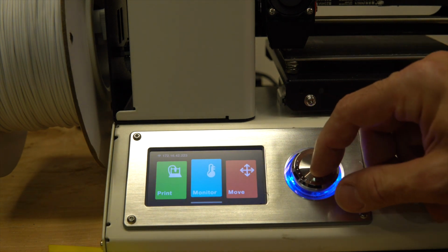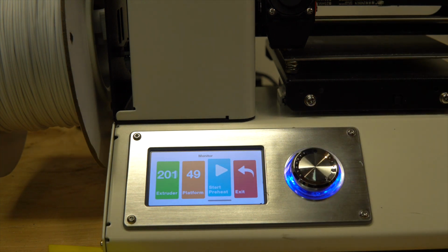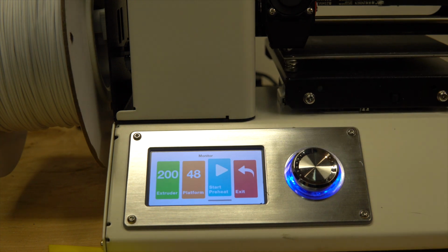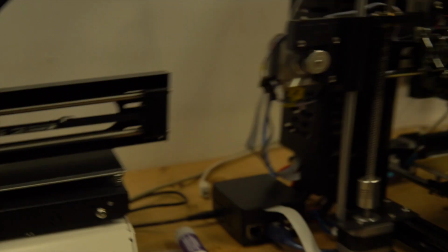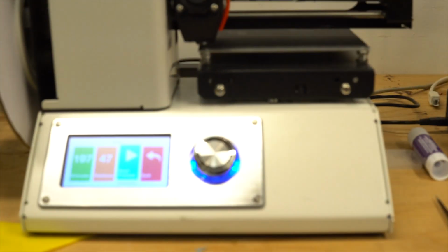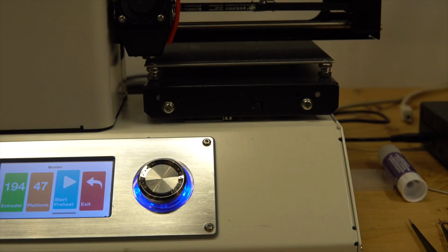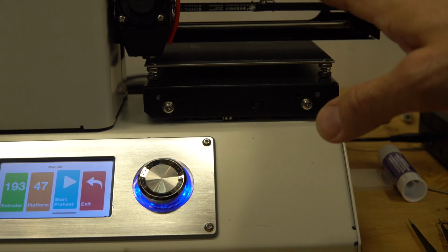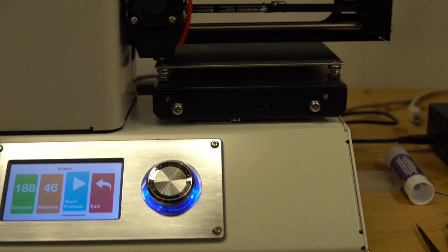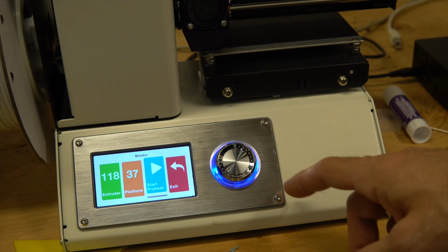Let's stop the preheat. So that's the bed leveling part of it. You know, you get used to it. It's nice to have an auto bed leveling like my other printer here. But since it's a small area, it's not that critical and it's not that hard to do. So it's level, and you do that every 4th print, 5th print. So let's try to print this ghost.